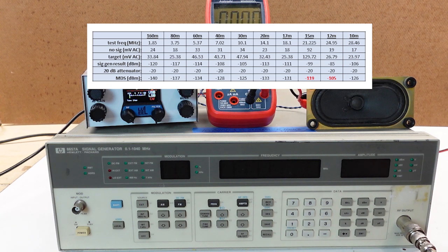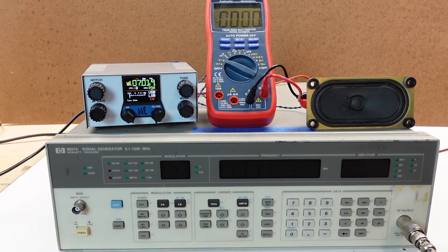Now, the two that weren't so good were 15 meters and 12 meters, and I think I know the reason there. When I was doing the fine-tuning of the bandpass filters, I really was getting either too much passband loss or not really able to get those filters to peak right where I wanted to. So in both cases, the signals were kind of going through the skirts of the filters, which is never good. So a little more work to do there, but otherwise, pretty happy with the performance.